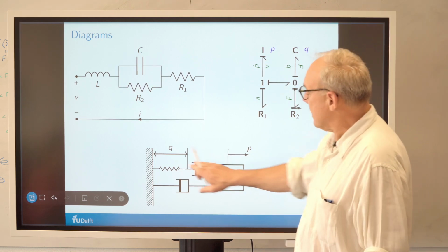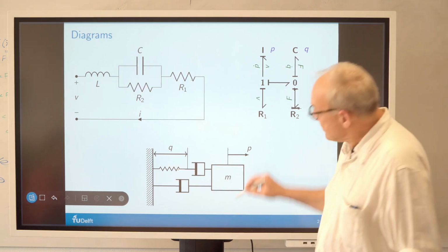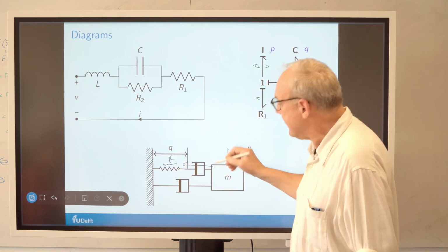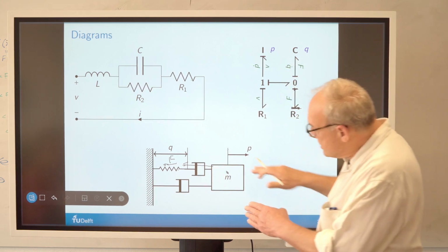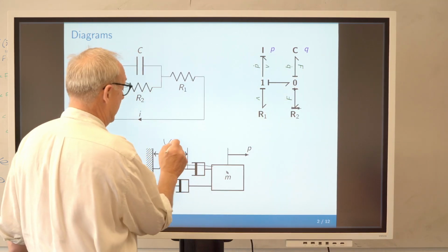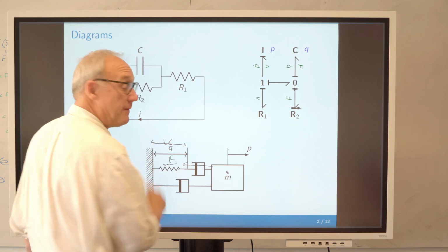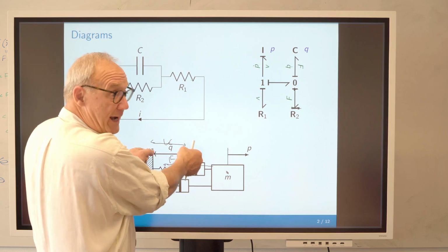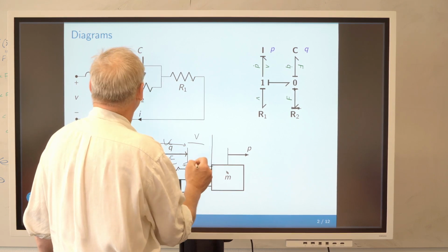Now, how would we measure the force going through this spring damper system? Well, we imagine the force kind of flowing through here, right? It's just this one force vector, and really it's a flow of the momentum decrease of this mass. So the force is going through, and the velocity of the spring would be right here, between these two things. We know from the principle of relativity that velocity is relative, so we look at the velocity of this point minus the velocity of that point. And this will be the velocity associated with this damper. What was that, R2?